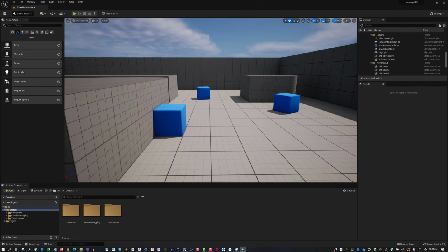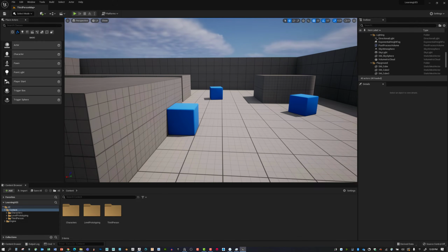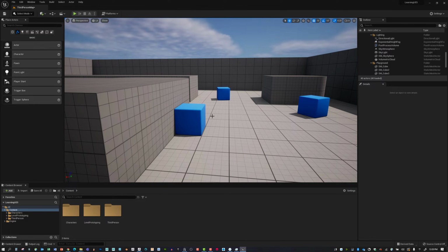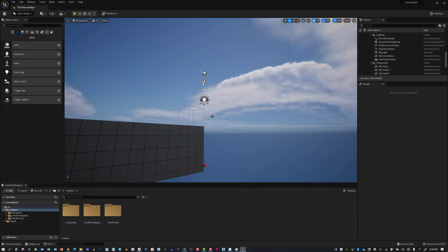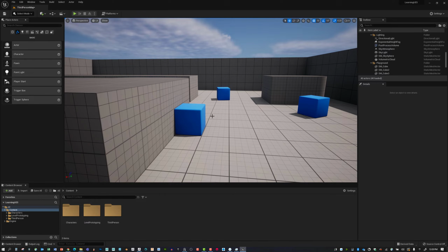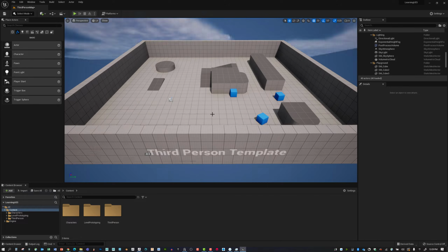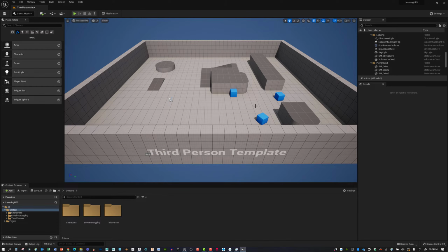So I'm just going to rotate with the right mouse button like this to look around after I scroll through and hit Control 4. So now I should have 1, 2, 3, and 4. So I've got these different views saved. So I would definitely set up some camera views at the very beginning, so that just makes it real easy to get back to these different views and allows you to work in this way.